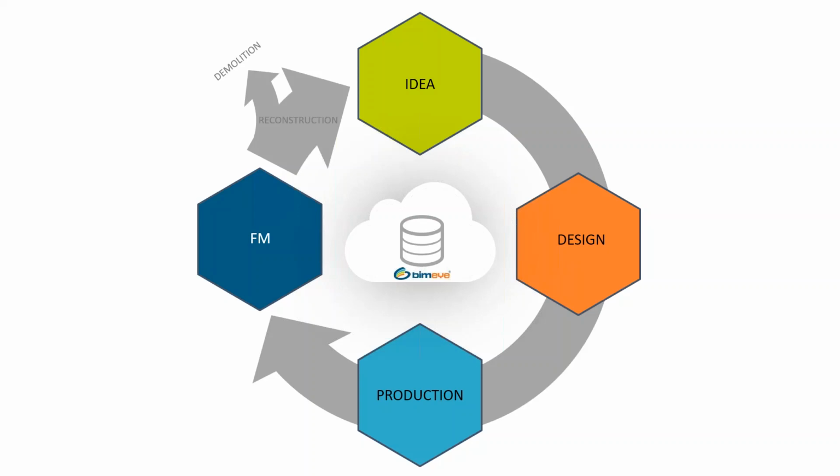And the machines must have the coordination of the piles, the X, Y, and depth, and the orientation of the piles, so that the work goes correctly. And when that work is done, when they have drilled and installed all of the piles, they will feed BIMEYE with the as-built data. So they will extract the coordination, or how deep the piles went, in the X, Y and Z coordinates, and they will extract that information from the building site, and send it back to BIMEYE again.